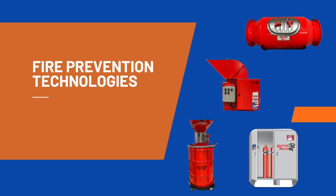So as far as fire prevention technologies, we can do many different things, including if you have return air applications, we can provide abort gates depending on if it calls out for that in the NFPA. If you're returning air back into the building, basically what the abort gate does is it shuts off that side of the duct and prevents fire, smoke, and burning material from entering the building.